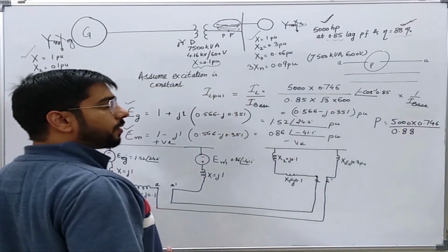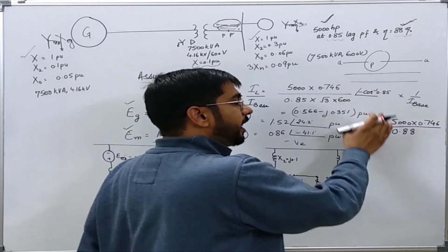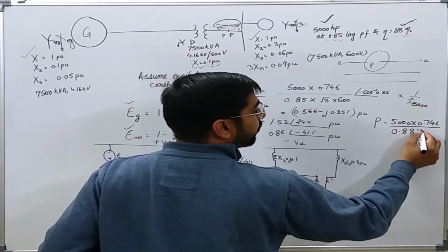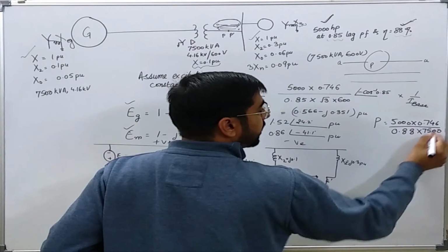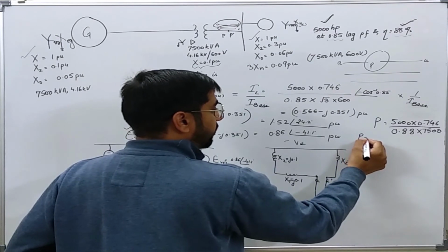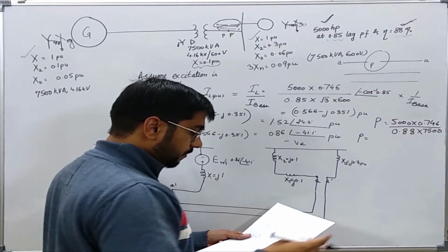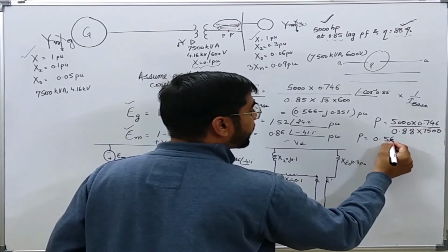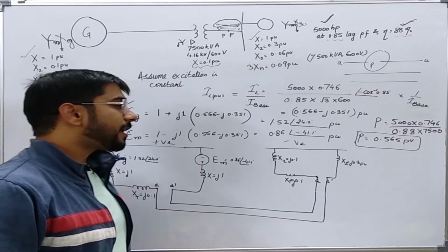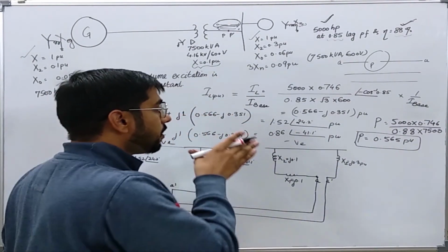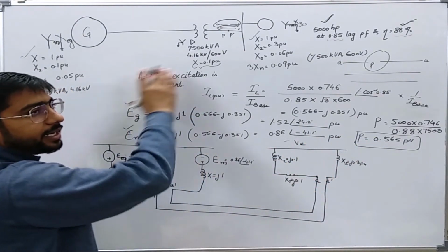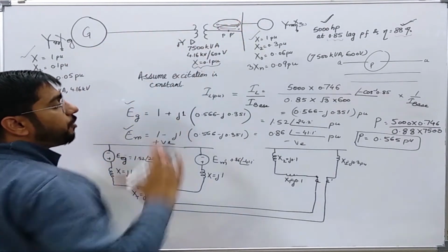using the efficiency. Okay, so this is the input power this motor is getting in the normal scenario, and if I convert it to per unit by dividing by the volt ampere base, I get the per unit input power to the motor in the normal scenario, and I have calculated it is 0.565 per unit. Okay, now the question is asking whether this motor can take this much power from the system when this phase A is now open.